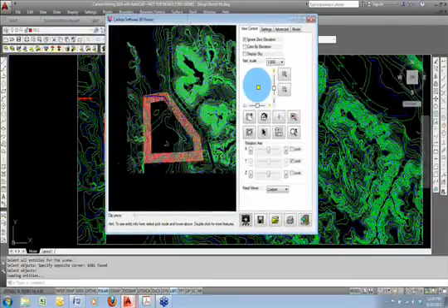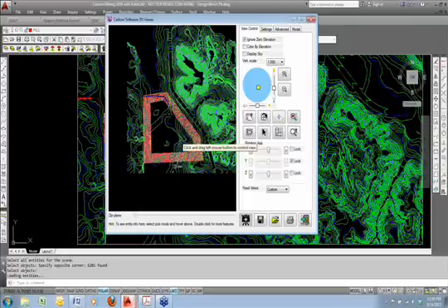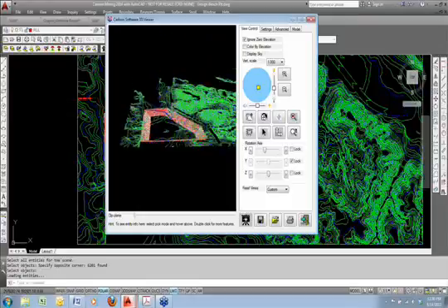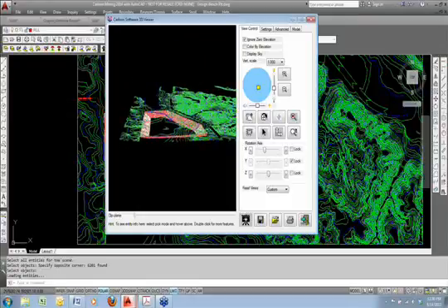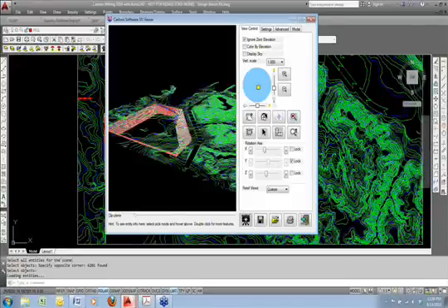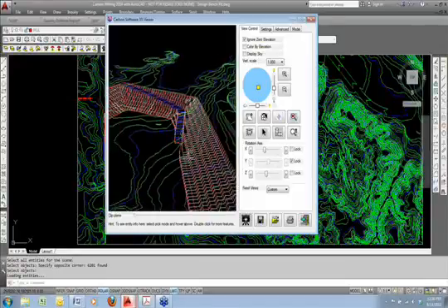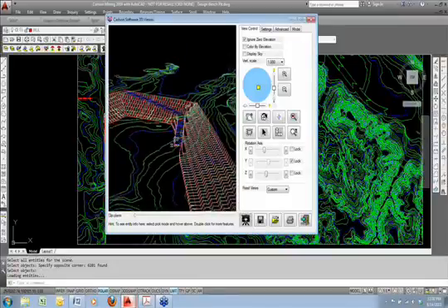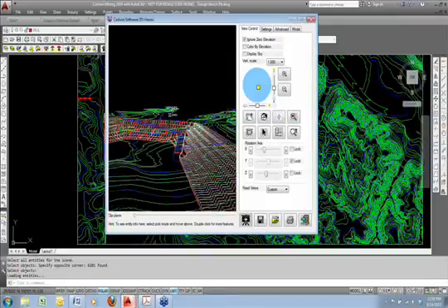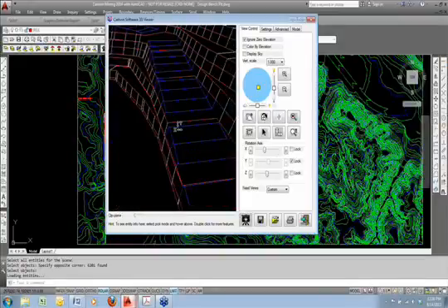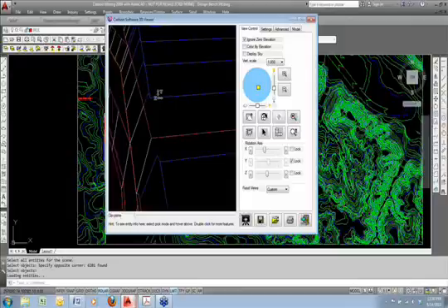Okay, this has changed also for 2014. For those that use this viewer, it's now similar to AutoCAD Orbit and Google Earth, where you push it up to lay it flat, and then you go to the edge and rotate it around on the Z-axis, and then press your wheel to hold. But the main difference there is the flattening in the X direction is now similar to standard Google Earth and AutoCAD Orbit. So zoom in on the edge of the ramp, and you should see there it is, the berm,